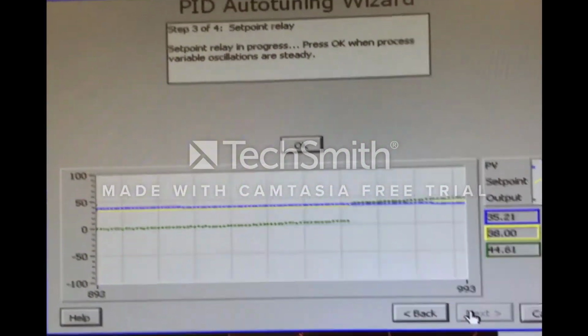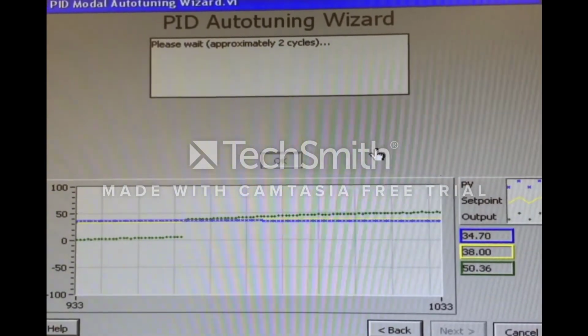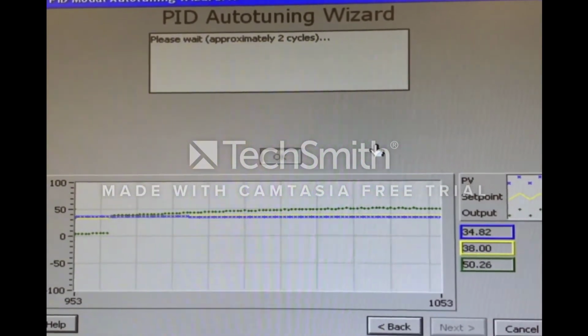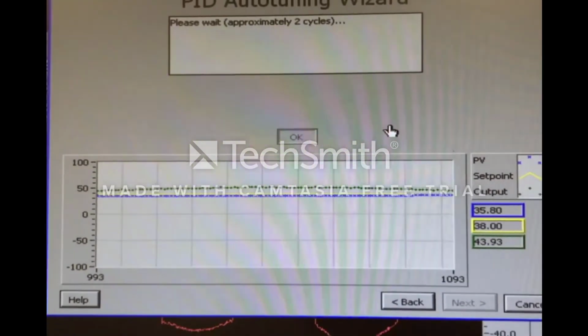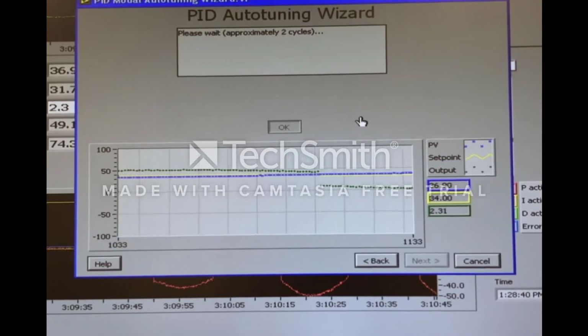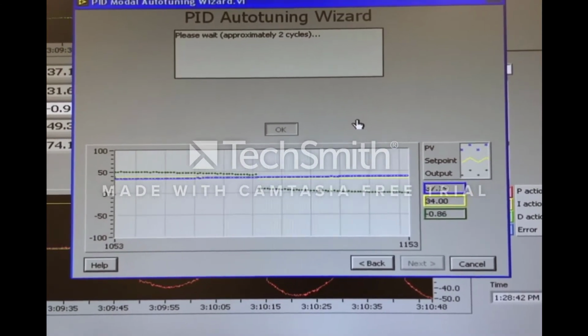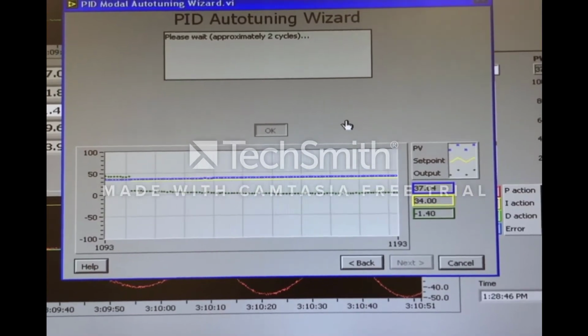Here I am going through a self-tuning experiment. First, I had the set point put at 5 degrees higher than the inlet temperature. The outlet cold valve position is on 5, the feed pressure is at 20, and then I use PI control with a KC value of 8 and a tau I of 0.1.